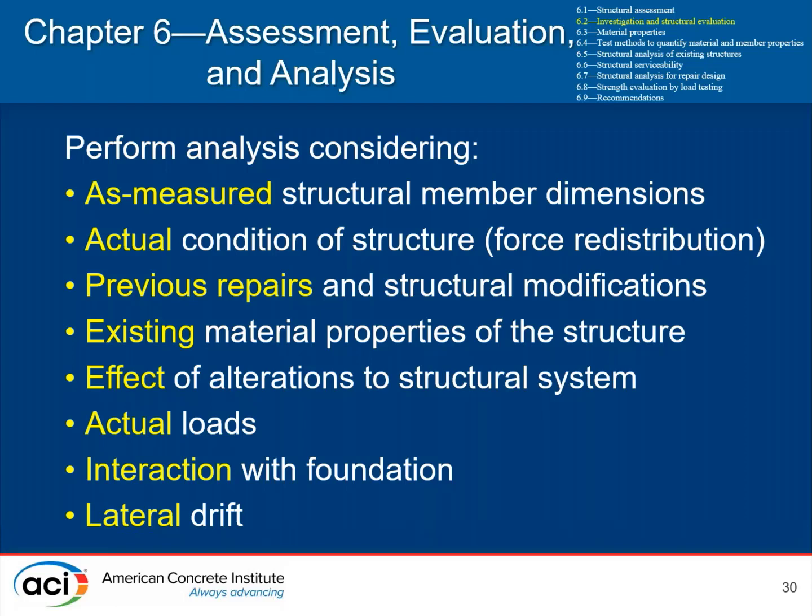Existing material properties of the structure, we talked about that already, and I think Mike covered that in Part 2 with regards to evaluating what the in-place conditions are, the effect of any alterations to the structural systems that were done intentionally, or maybe perhaps even those that have been less intentional. Actual loads in accordance with the structure, and then interaction with the foundation and lateral drift. These are all things that should be evaluated as part of a performed analysis.